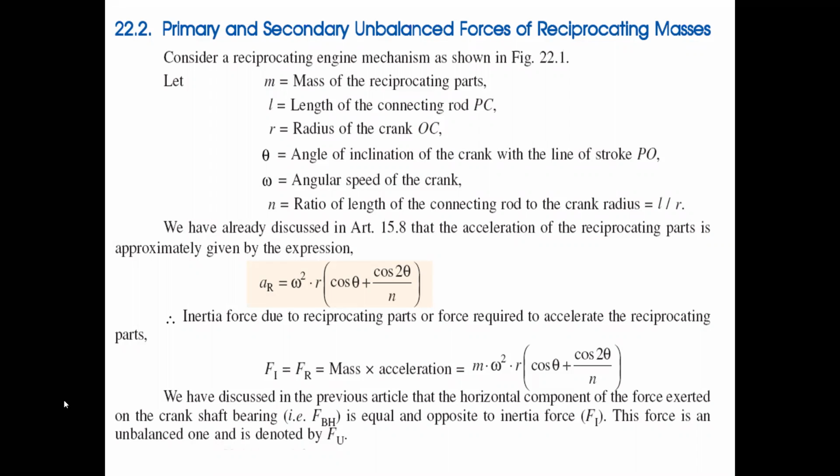So now we will find the inertia force due to the reciprocating parts, or the force required to accelerate the reciprocating parts. That value is the inertia force, which equals the force required to accelerate the reciprocating parts. Both are equal. Why? Because when we start the engine, the resultant force overcomes the inertia force. That will definitely happen.